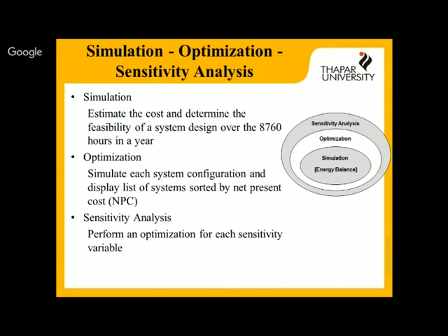And sometimes suppose I am using DG only, so I don't need a converter, as that is connected to the AC bus only. With DG, obviously the cost will be more. If I'm meeting all the load electricity demand from DG only, the cost factor will be one issue. I can use DG plus battery, or DG plus battery plus PV. So many options. It simulates all the options for you, and it ranks them according to the cost of electricity.